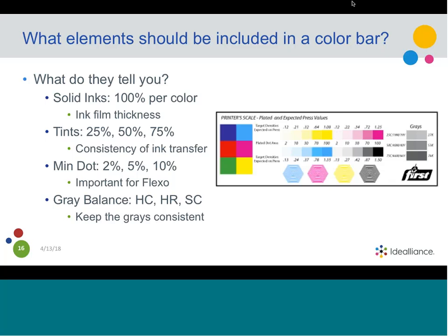And then the min dot, particularly important to flexo because of the way flexo plates are made. The small, very small highlight dots can break off and not print properly, so it's good to be able to gauge exactly how well the flexo plates are printing in the lighter areas.